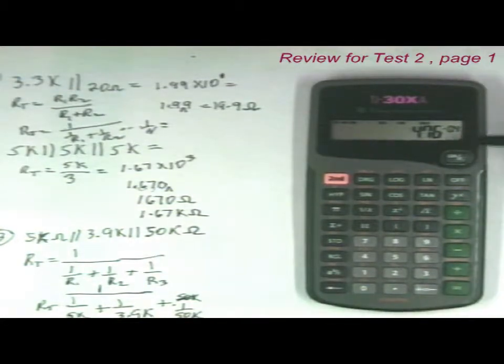Now notice up here that we have a negative number. That tells you you're not done yet. We're normally not going to have a negative resistor. I'll go into that another time, but normally in this class you will not see a negative in the powers of 10 as far as the resistors go. You will in current, but not for resistors. So if you get a negative in resistors, just know that you're not quite done.